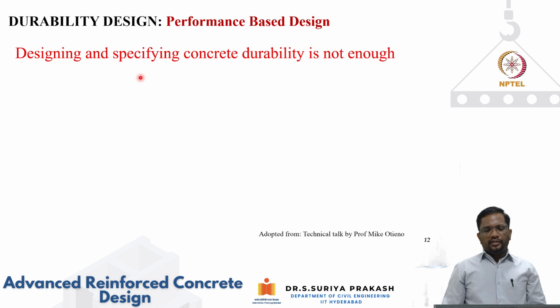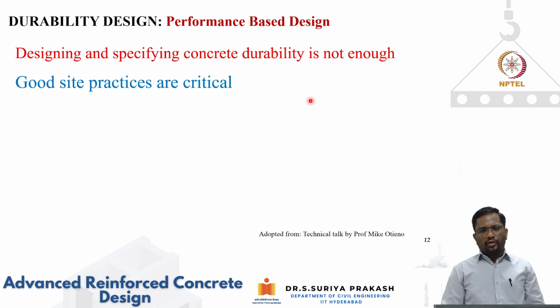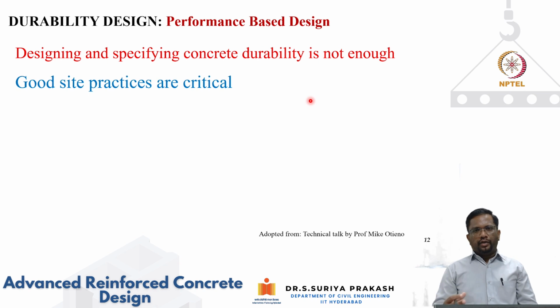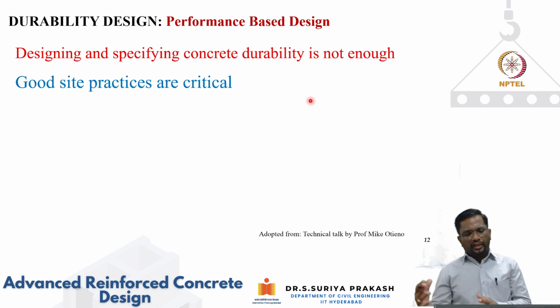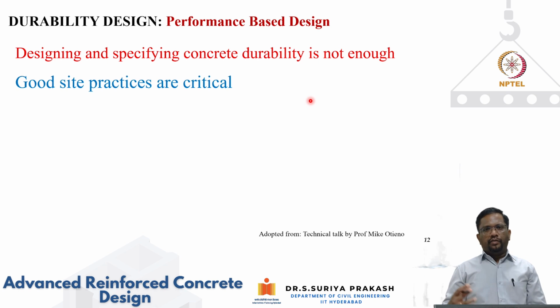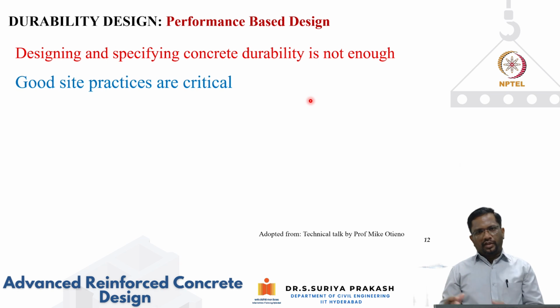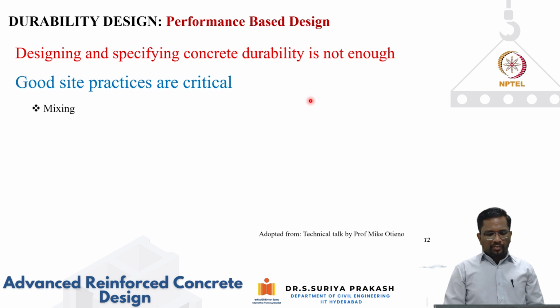Okay. Now, again, designing and specifying concrete durability is not really enough, and good site practices are critical. Again, we kept talking about it. You may develop a good concrete in the lab, but if that mix design, when you scale it up on the site, is not executed properly, then you will have very different concrete on the site. That's why it's very important to test samples from the as-built structure to see whether you are meeting all the requirements. Also, cover. We keep talking about cover, and whatever cover you have specified in the drawing should be exactly executed. So that also is important. So good site practices are important.